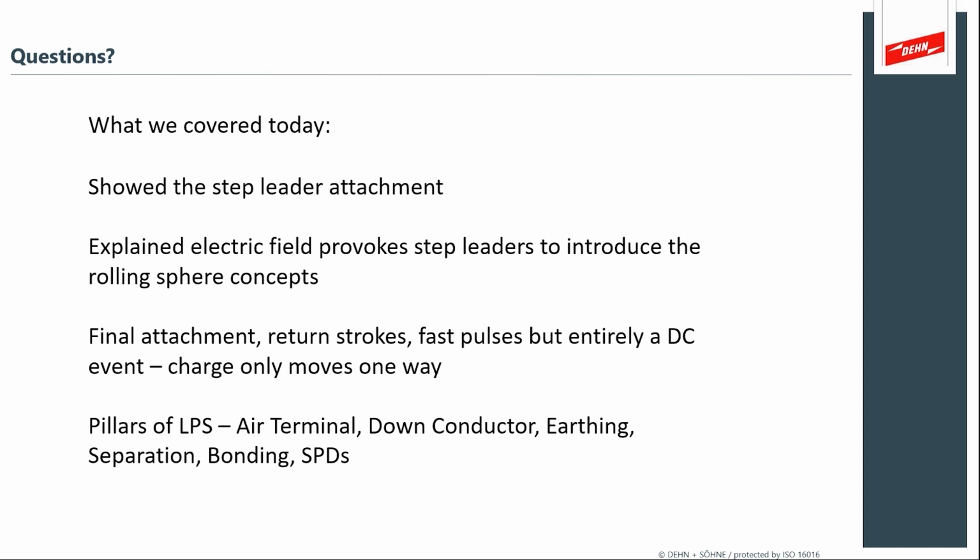I'm glad you mentioned the NFPA. The question here is, can an NFPA or an ESE system provide a protection zone, and can it be determined with the rolling sphere? Thus, can I assess an NFPA system with the methods in IEC?